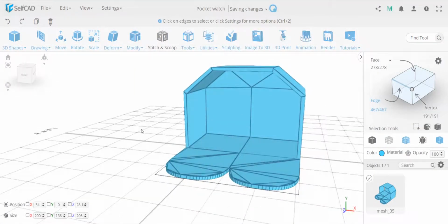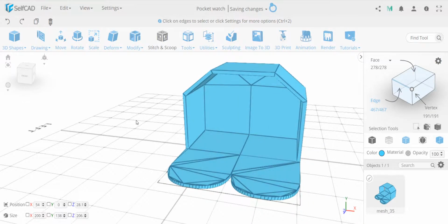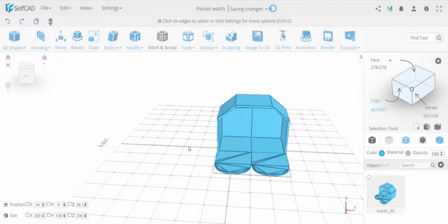This is actually very important, because when you work with extrusion or add thickness, sometimes you have to use positive, sometimes negative, and sometimes it works counter to what you think. You think negative would go inside and positive would go outside, and sometimes it works the other way around. That means the object is flipped, and you have to use flip normals.